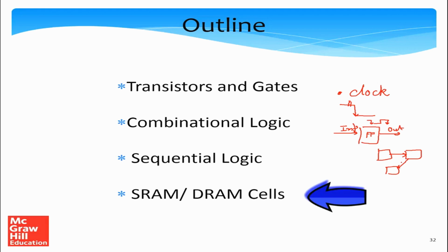Our main aim in this chapter is to provide an overview. Then we will move to the next part of the lecture, which is memory cells. So what is a memory cell? In a memory cell, we can essentially store a lot more data in a fairly compact form. A flip-flop actually requires a lot of transistors. It's a very nice and fast structure, but it requires a lot of transistors. As compared to that, a memory design is far more compact. So for the same area, it allows us to save far more data. We'll take a look at memory cells next, in the next lecture.